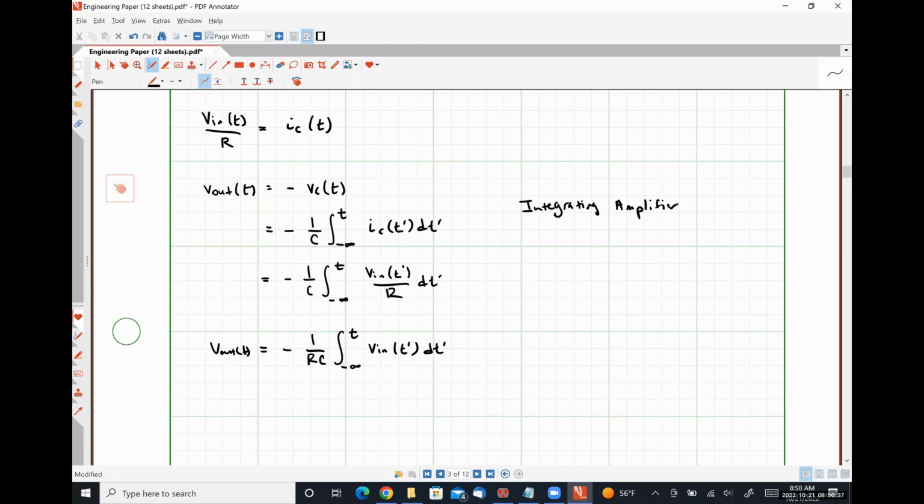I am not writing the inductor and capacitor problems. That's Dr. Cronk and Dr. Swanbaum's deal. And then for the transient analysis stuff, there's going to be 1 circuit that's an RL circuit and 1 circuit that's an RC circuit. And it'll be broken down into multiple steps that effectively line up exactly with the way that I taught you how to do it. Figure out what's going on at 0 minus, figure out what's going on at 0 plus, figure out what's going on at infinity, calculate the time constant, plug stuff in.